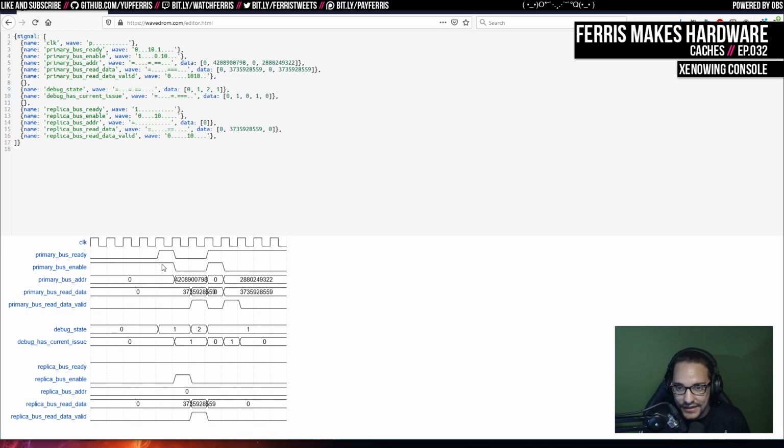And this whole time, the test harness is trying to issue a read to address 0, it looks like. On the cycle following this read, instead of returning data, because the cache doesn't have that data in it since it's all invalid, you can see that the cache after invalidating goes into this ready state. I think it's the active state. And you can see here, once it accepts that read,